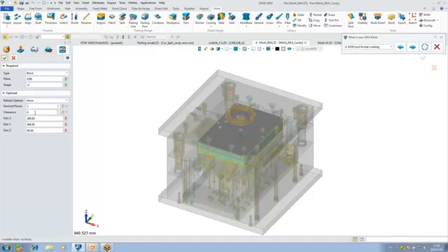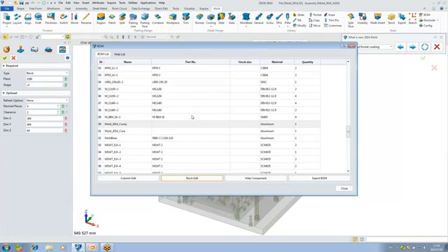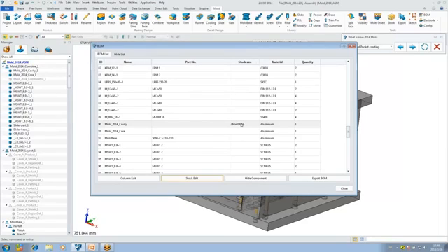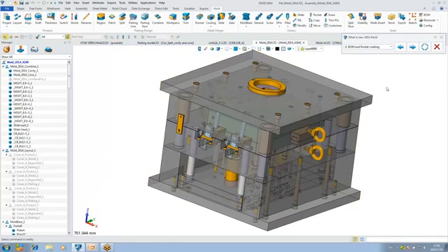What's more, in the new version, we support the decimal place and the clearance. Right here we can set the decimal place to 0. So here you can see the XYZ direction value has been changed, and we can also change the clearance, because most of the time the workpiece for the part we always need to make a little bigger. Just click OK, it will go back to the 3D BOM interface, and here we already assigned the slot size for it.